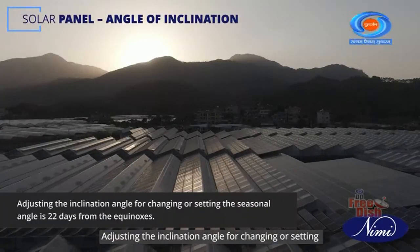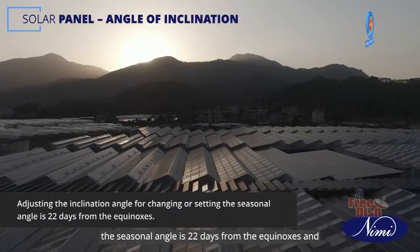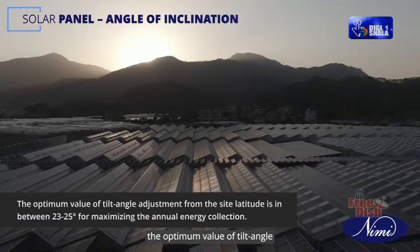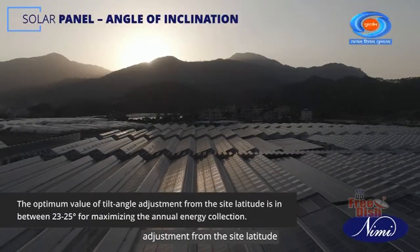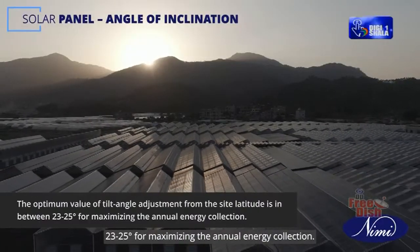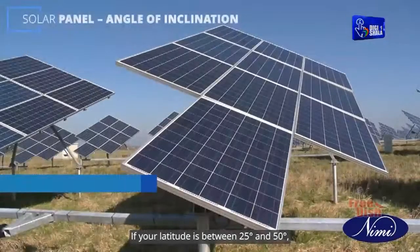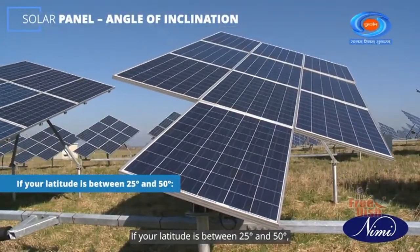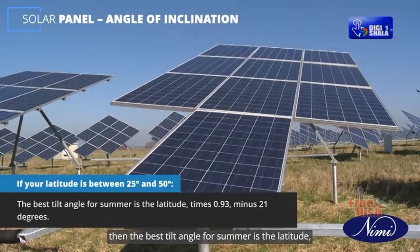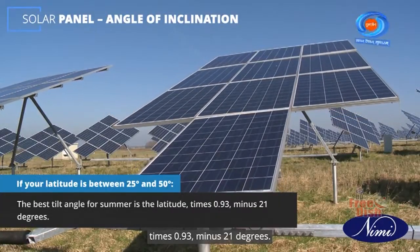Adjusting the inclination angle for changing or setting the seasonal angle is 22 days from the equinoxes, and the optimum value of tilt angle adjustment from the site latitude is in between 23 to 25 degrees for maximizing the annual energy collection. If your latitude is between 25 degrees and 50 degrees, then the best tilt angle for summer is the latitude times 0.93 minus 21 degrees.